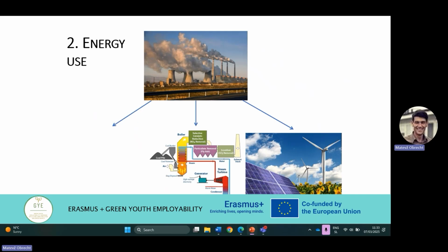So what if we would somehow be able to do something efficient with that waste energy? This is the idea of cogeneration. By creating electricity and heat simultaneously, we can increase efficiency from 30 to 40% up to 70 or even 80% in theoretical cases. So this is the way to, let's say, double the efficiency of use of fossil fuels.